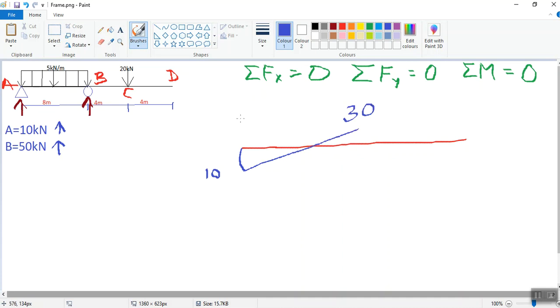Then the support reaction at B is 50 kN in upward direction, which gives us 30 minus 50, 20, so shear force again changes direction, to positive 20. Then it goes linearly to point load at support C, 20, and 20 kN load acting in downward the shear force finally to 0. So this is shear force diagram, and let us name the supports A, B, C and D.